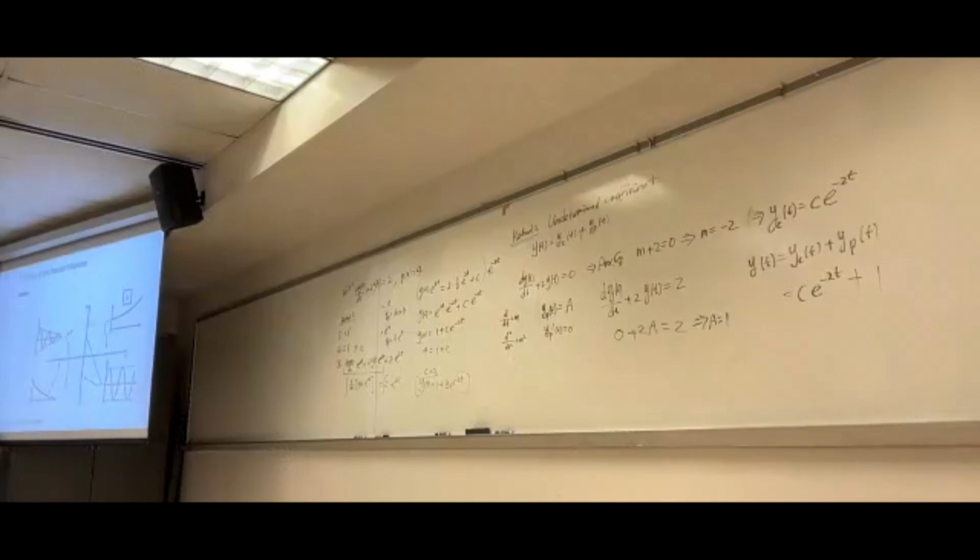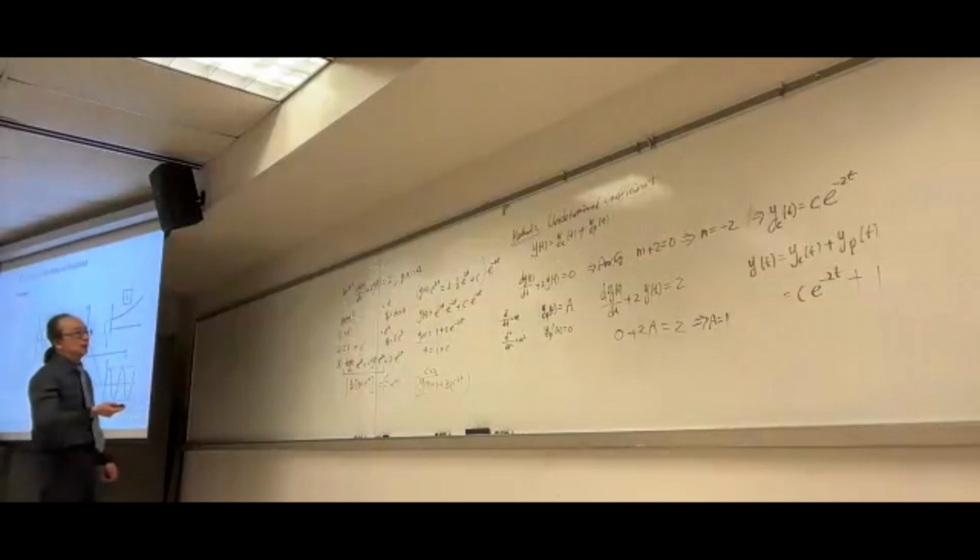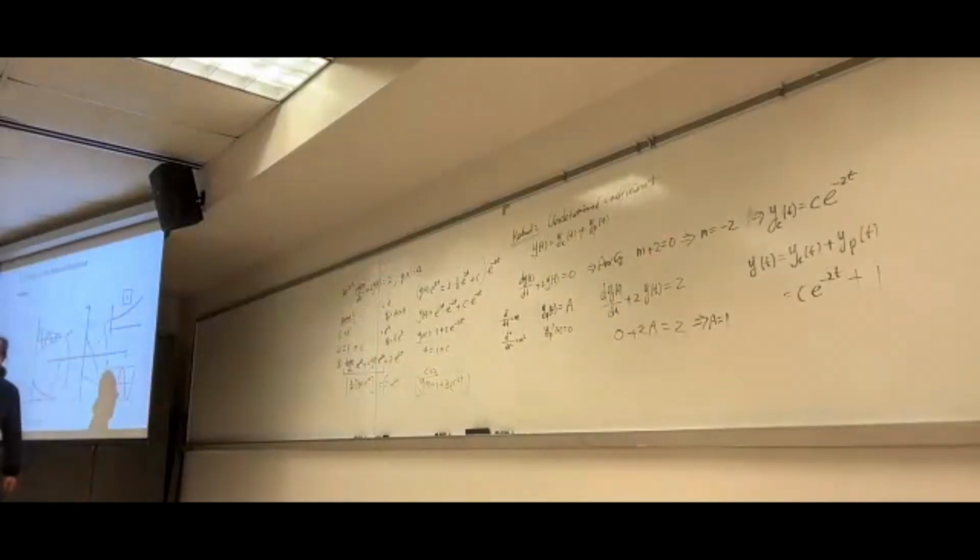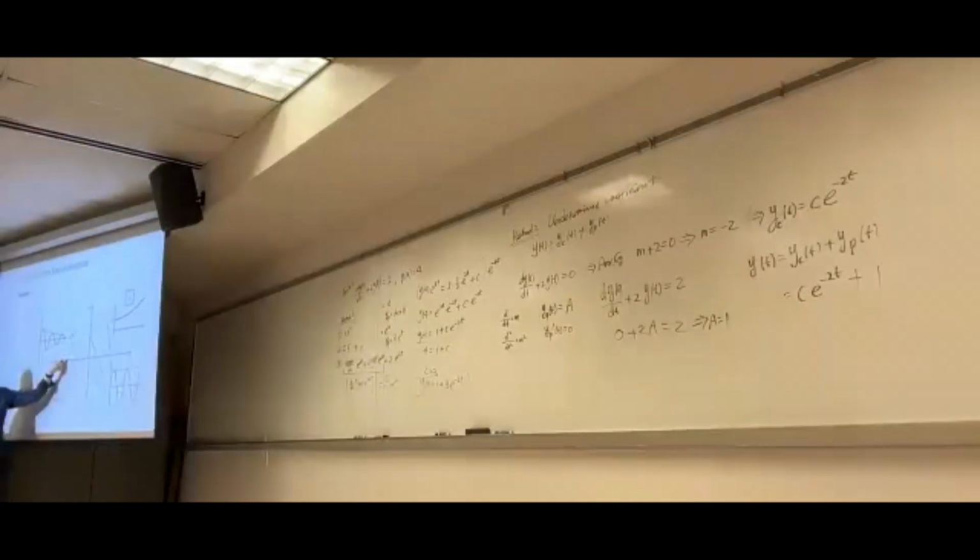For any given differential equation, we let the left side equal 0 for the auxiliary equation and find the roots of that equation. If the roots are on the negative real axis, like the negative 2 in this one, then it is stable. For a second order differential equation, the auxiliary equation might give us negative 5 plus or minus j2, a complex number.